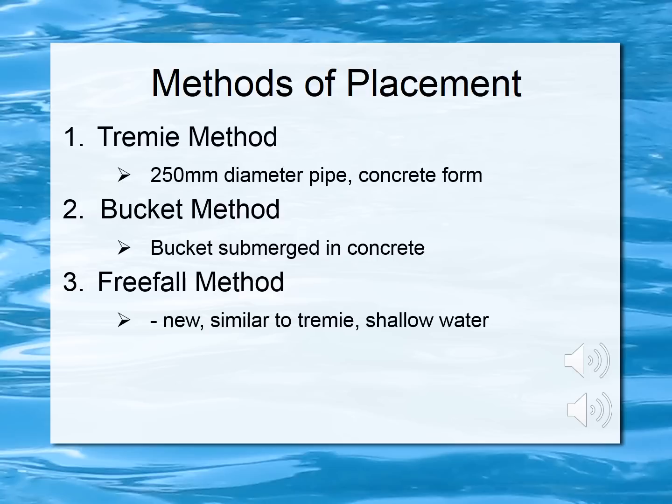This is something that isn't as prevalent yet in the industry. It came about recently, based on technology advancements, using a Tremie pipe and into your formwork to control the properties. It's a little bit of setup work, but it pays off in the long run. And this is generally done in shallow water at this time, and they're looking at ways to expand it into bigger concrete pours and make it more cost-effective to pour concrete underwater.